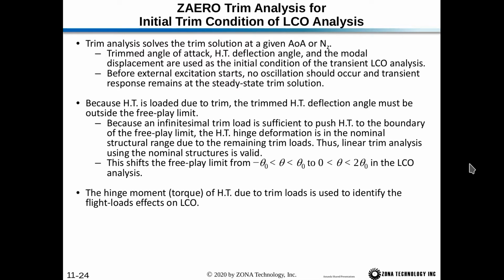So next we'll do a trim analysis. The trim analysis solves the trim solution at a given angle of attack, or NZ. The trimmed angle of attack, horizontal tail deflection angle, and the modal displacement are used as the initial condition of the transient LCO analysis. And before external excitation starts, no oscillation should occur, and the transient response remains at the steady state trim solution. Now, because the horizontal tail is loaded due to trim, the trimmed horizontal tail deflection angle must be outside the Freeplay limit.